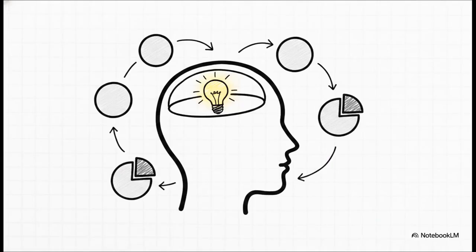Well, the answer is actually incredibly practical. There's absolutely no physical grid requirement forcing the number 100. It was chosen purely for mathematical convenience and easy mental math. Because the base is 100, dividing or multiplying by it is basically instant. It translates decimal per unit values into percentages right in your head. If you're looking at a 12 MVA transformer and your system base is 100 MVA, that transformer's capacity reads instantly as 0.12 per unit. You know at a glance it represents exactly 12% of your system's base capacity. That human convenience is the entire reason 100 MVA became the industry default.